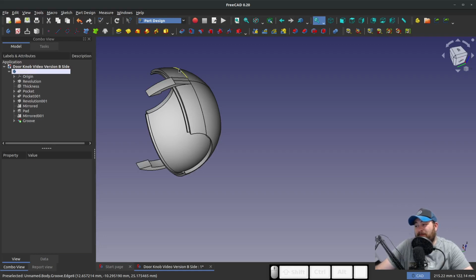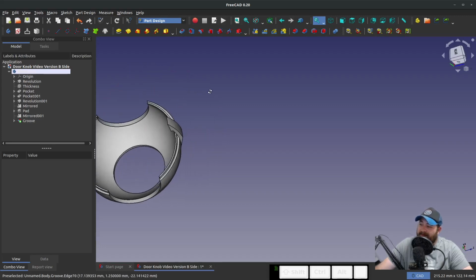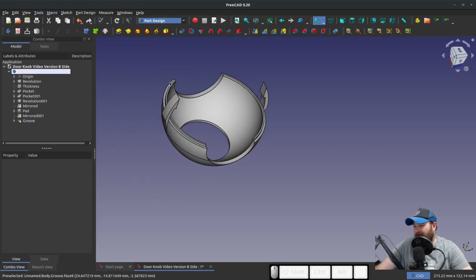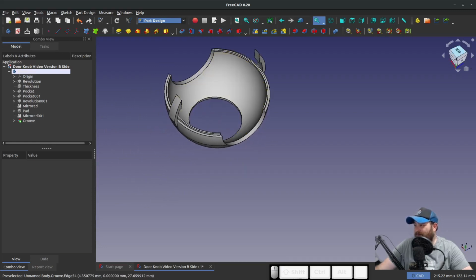You also can make the snaps internal, right, and have them facing to the outside, and that might save you a little bit. But I wanted mine to be pretty easy to take apart without much thought or effort. So I designed it with the snaps on the outside, so it's pretty clear to see the design and how to get it apart. Now it's time to print it, and we might want to go through meshing the part.